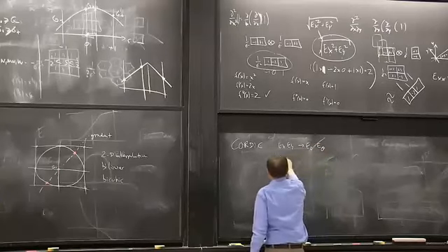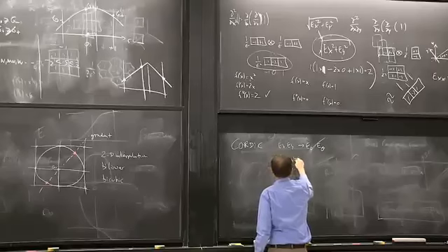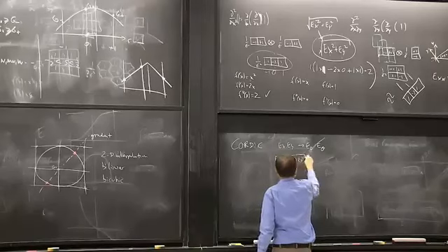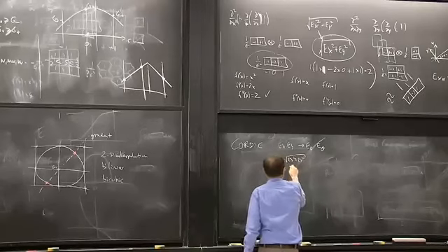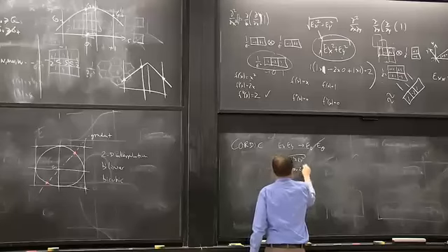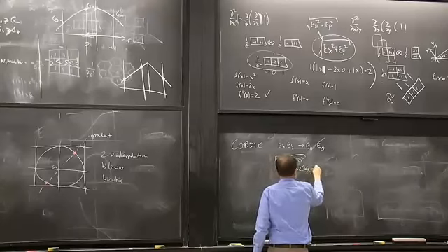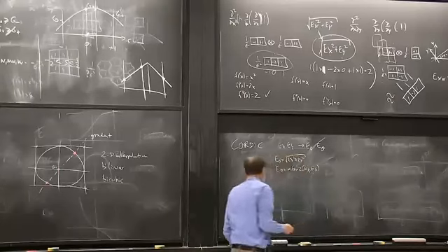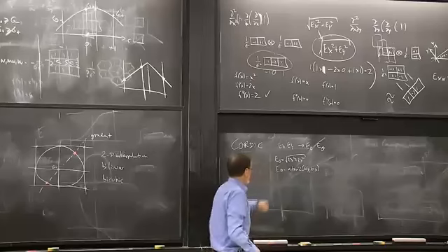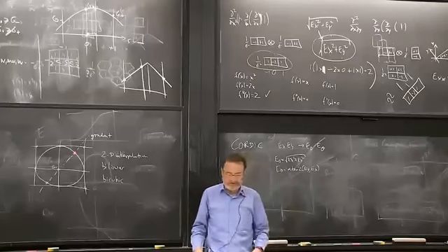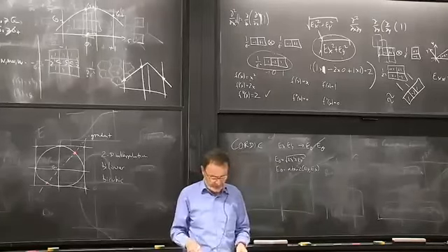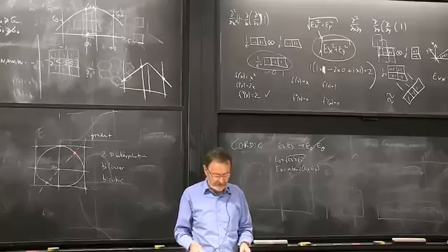So it's just a Cartesian to polar coordinate transformation. And square roots and atan take some computing. You'd have to probably use a lookup table to speed that up.